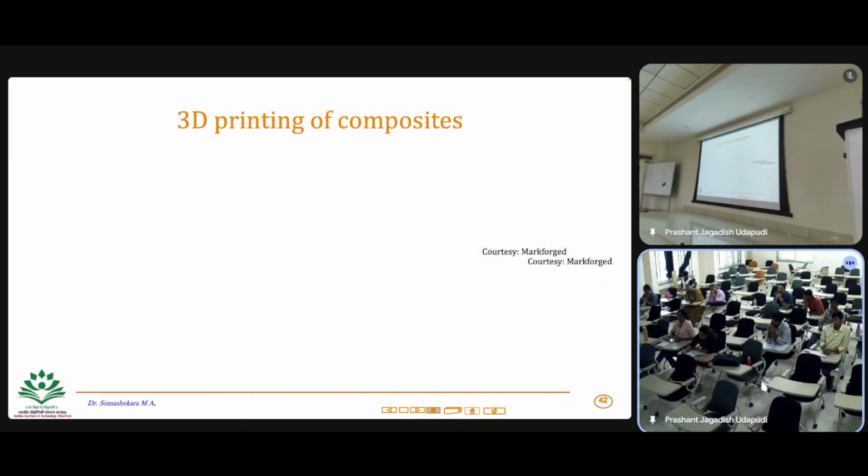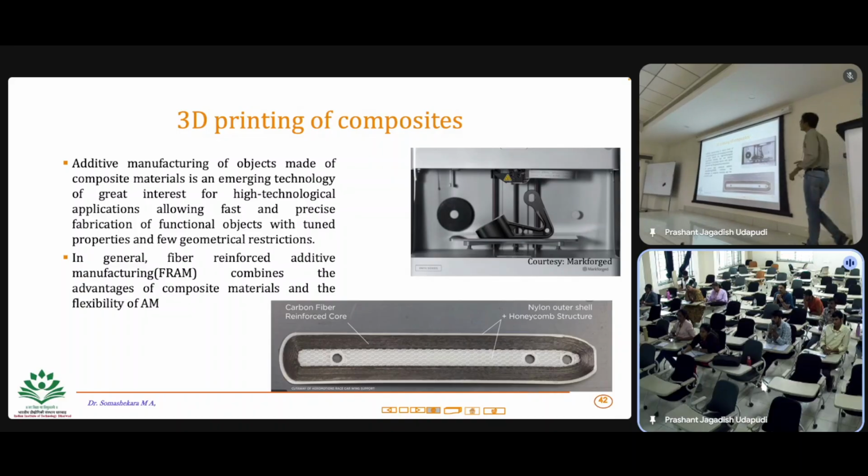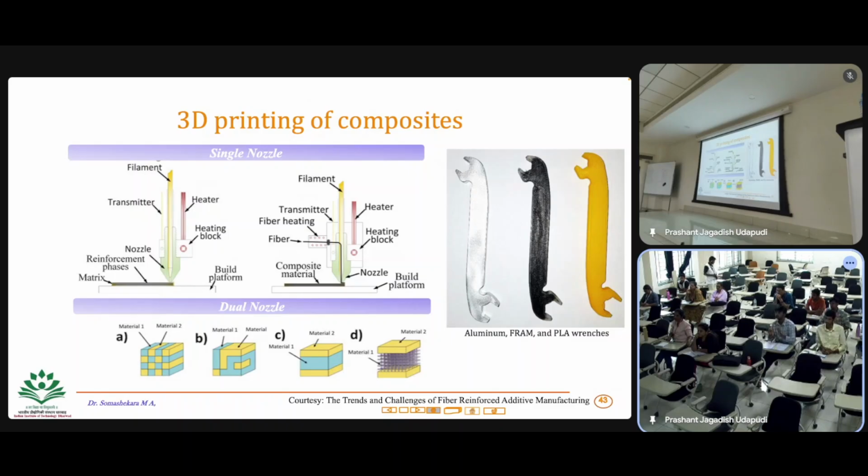especially in ABS, because it is very sensitive if you compare it to PLA and the like, right? I think a lot of composite structures are being explored nowadays when it comes to 3D printing, especially when you want to have, for example, carbon fibers or a reinforced core, and a lot of people are even using short fibers and long fibers for making the component. You can have a dedicated nozzle for that, or you can prepare a filament made of a composite structure or composite materials, right? And that filament you can use for fusing the material, right? So as I said, there are different ways in which you can fuse the carbon fibers.